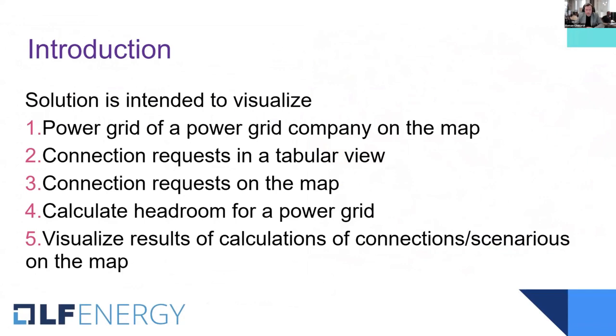You can choose this connection request on the map. You can calculate headroom on the power grid. Headroom is a special word which represents the possibility of the power grid to connect additional connection requests. So this connection request can be of 2 types, production and consumption. We calculate both of them. And in the end, we just visualize the results of the calculations.